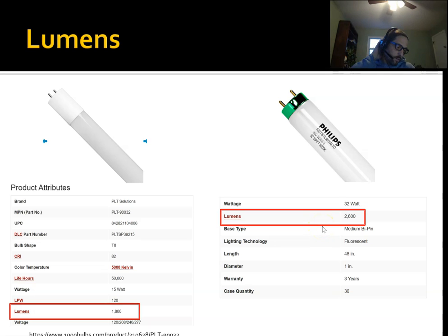So whenever you're making a lighting replacement, you do want to look at the spec sheet. You do want to check not only the size of the lamp, but also the color temperature, but the lumen output is important too. There are some other considerations. It's not quite so simple because of the directionality of the light. For example, with the T8, the light is going in all directions, right? So some of the light is going to go up, and so you may lose some of that light, because it's not going down toward where you want it to go.